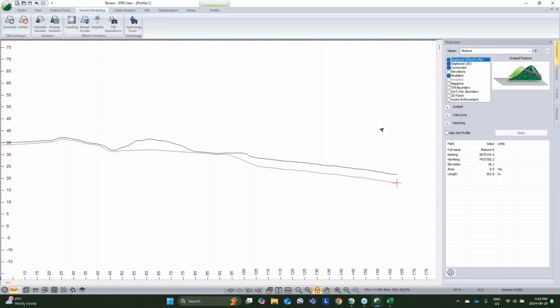So the skill set here is very similar to if we're editing a surface with conventional survey data, where we might add break lines in to get what we'd like. Now, if we had a point up here and a point up here with a depth, well, we probably wouldn't want to just have an interpolation that runs from there to there, because we'd end up with surface data above our actual topo. So for me, I like to use the regular grid function of the software and run with that.